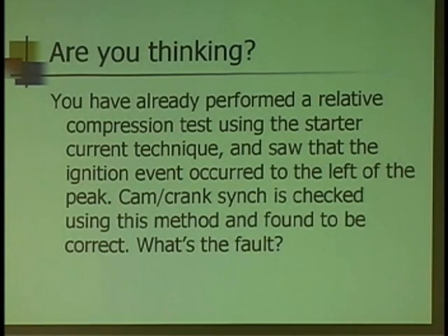The crank doesn't care. TDC is TDC. But if the trigger for the crank sensor is on that flywheel or on that harmonic balancer and it's spun on the crank, it hasn't lost its relationship with the cam, has it? And the ECM says, okay, that's when I need to fire it, and I'm going to fire it then.